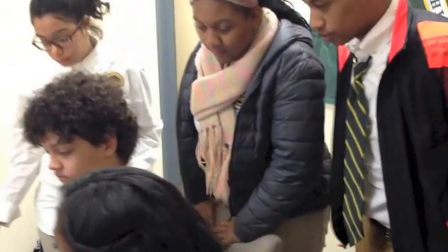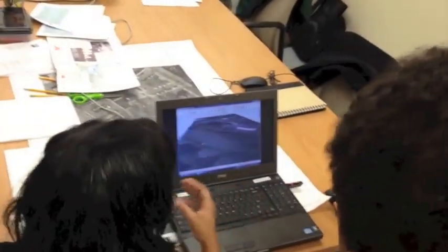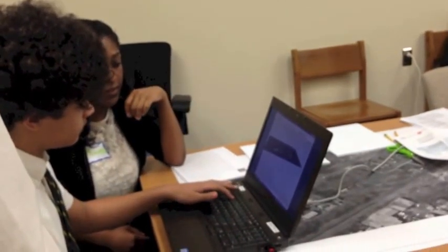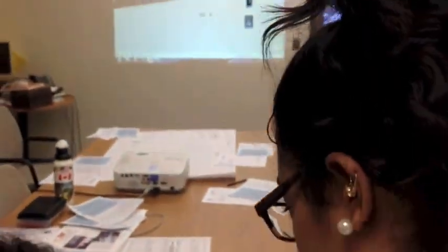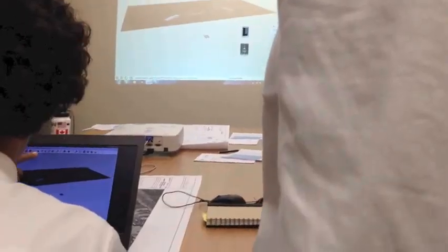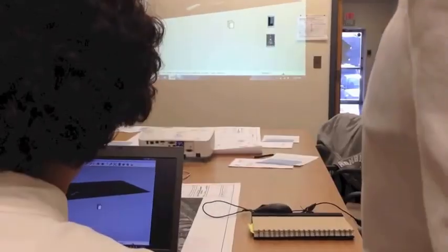That one moves it around like a pan, and then to rotate the mouse, you use the middle piece, the little wheel, you click it, and then you can orbit around. So that's how you move around the program. So then, depending on what size it is, you enter the dimensions, you type it into the keyboard, and then you get your box. And then you can push and pull and extrude these surfaces to get them the size and the form that you want them to. That one right there, you just click on it and then pull it up.